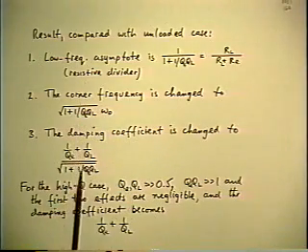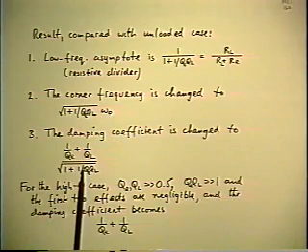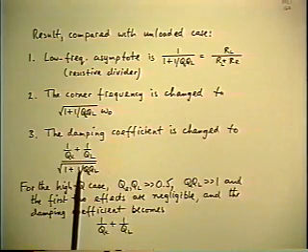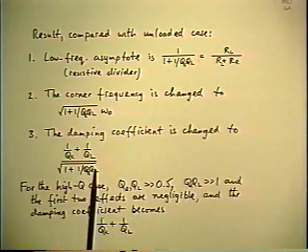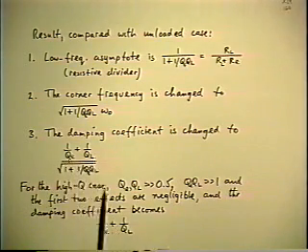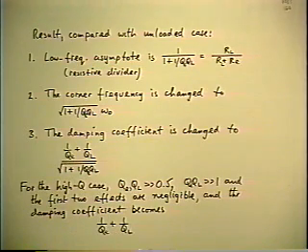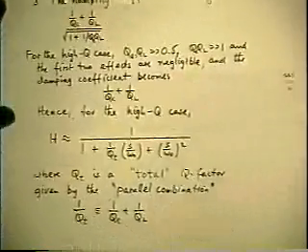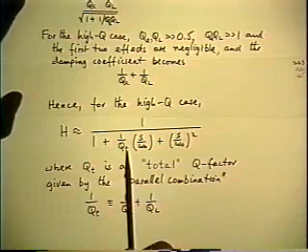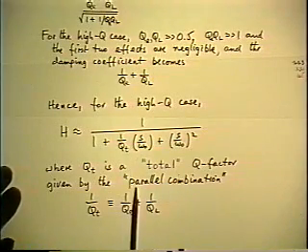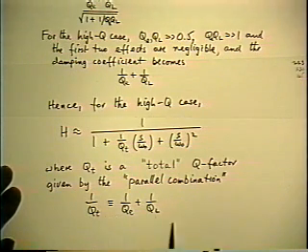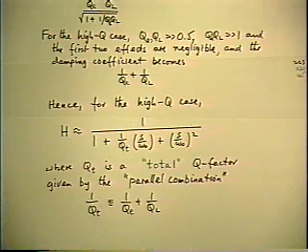Now there's still a third effect of the damping, of the loading I should say. And that doesn't go away with the same restriction, but it gets simpler. Because again, it has the same factor showing up, but that isn't the only thing that happens. So you can make this factor essentially 1, and what you're left behind with is 1 over QE plus 1 over QL, which is the same thing as defining a new total Q factor which has this derivation in terms of the other two. In other words, it's reciprocal sums, and it's just like the parallel combination of the two contributions.